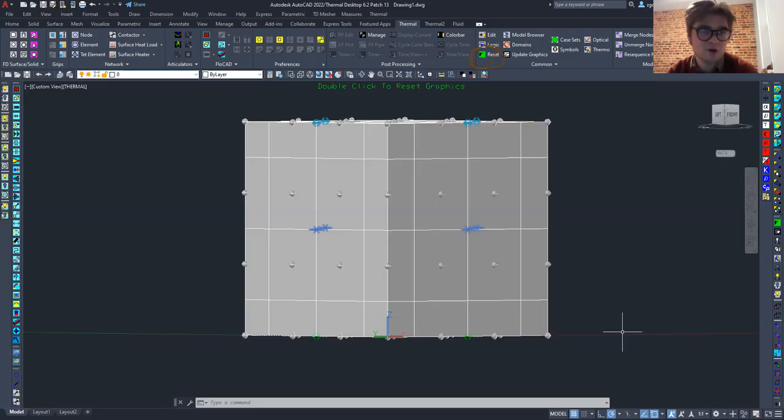I haven't put this cube in orbit. I haven't done anything that's actually going to simulate temperatures. And even if I tried to do that right now, it would throw an error at me because I have defined no thermophysical or optical properties. If you're doing radiation, then you need to have optical properties defined. And if you're doing conduction, which you always are, you need thermophysical properties defined, which is your thermal conduction, your density, and your specific heat. And on the radiation side, you need your absorptivity and your emissivity.